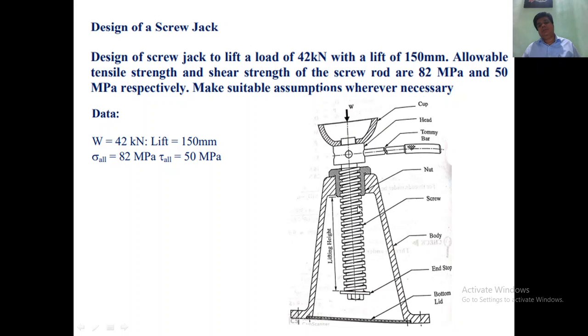All of you have seen this screw jack, and maybe many of you have used it to lower or raise a load using this handlebar. Design of the screw jack means, first, we should specify the dimensions of the screw thread, what the pitch should be, and what the diameter should be. The material properties are given, and you have to calculate the dimensions for the screw rod and also the dimensions for the nut here.